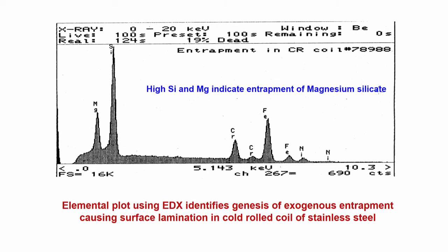So, energy dispersive analysis of X-ray, the whole idea is to discriminate the energy level of X-rays generated from the steel sample and from the defect area, from the entrapment, to know what elements are present in that constituent, in that non-metallic inclusion. In steel we know what elements are present, but in the non-metallic inclusion, let us see.